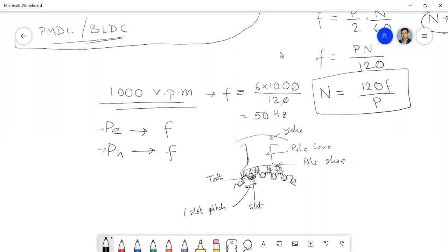Okay, now here the pole is fixed. When this portion is rotating, then what happens? When this tooth leaves this portion, there will be a sudden change in the magnetic flux in this portion. So there are several portions in the pole shoes where you have this type of flux change due to the flux swinging. This phenomenon is called flux swinging.